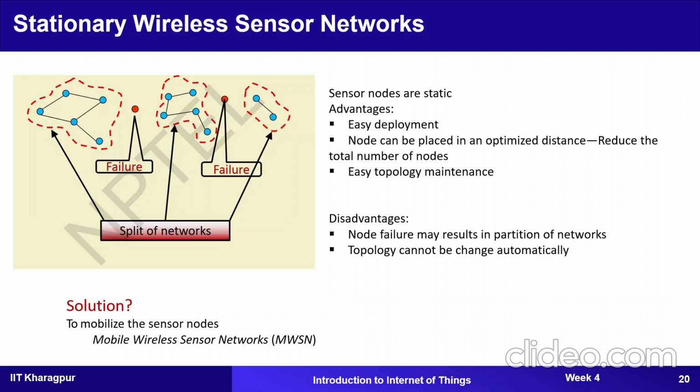However, on the other hand, your mid end sensor nodes are more expensive as compared to your low end sensor nodes. They can be mobile, however fewer constraints with respect to complexity and energy efficiency is there. Additional functionalities, so basically the functionalities which are provided by your low-end sensor nodes are there, and apart from that, functionalities such as your localization, quality of service, TCP/IP support, power control and traffic control intelligence are also there in case of your mid-end sensor nodes. These are typically used for home network, SCM, supply chain management, asset management and industrial automation.